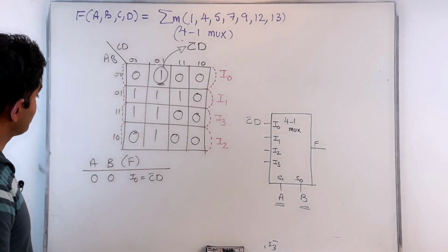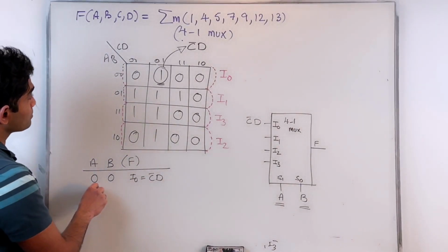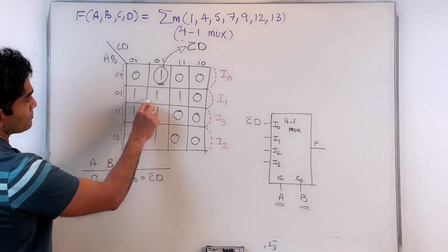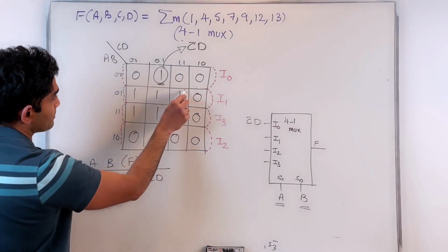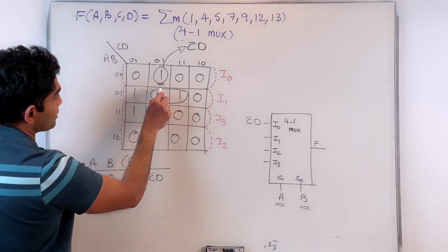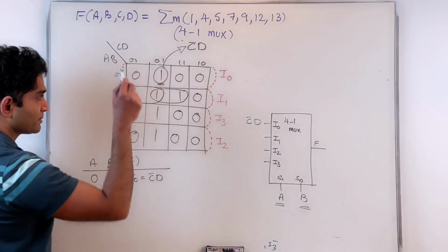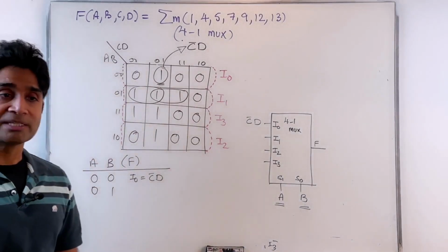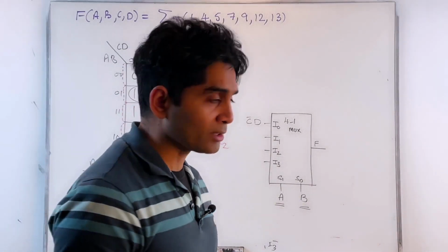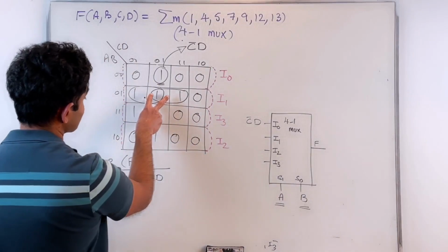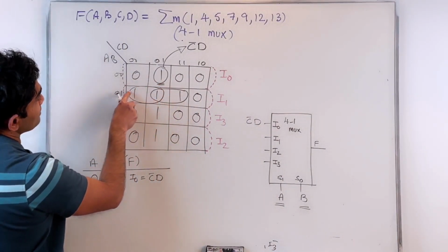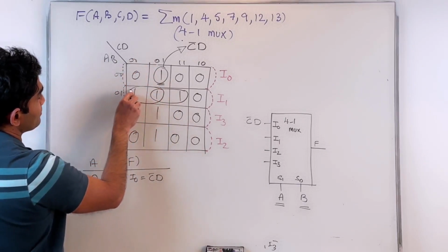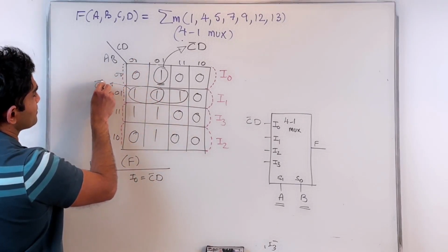Okay. Now AB of 1, 0 or 0, 1. In this case, again, that's my sub K-map. I'll combine these two adjacent ones along with these two adjacent ones and read out the product terms in terms of C and D only. So I have two product terms. In this case, that corresponds to C prime.